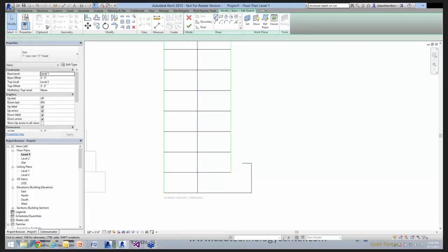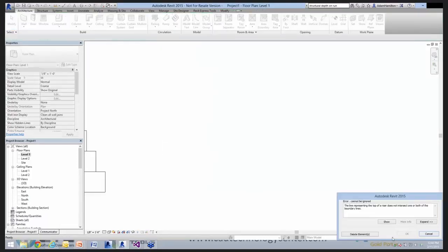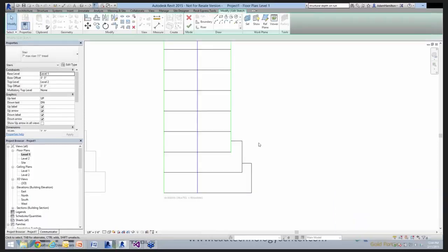And so if we were to do this, and then if we were to try to do that with the second tread in the same manner, riser line, it does not like it. Typically, you can only get away with the first tread being wrapped. If that's something you want to do, now all of a sudden you have to think about maybe making tread families and modifying those independently.